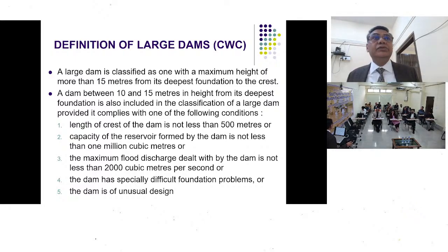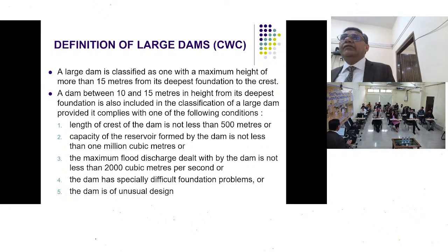There are shear zones. There are varied types of rock. Maybe the most suitable location which you identify to have your dam constructed consists of two or three types of rocks coming in the foundation of the dam, and the deformation characteristics of all those rock types are going to be different, and so my dam structure is going to behave differently.